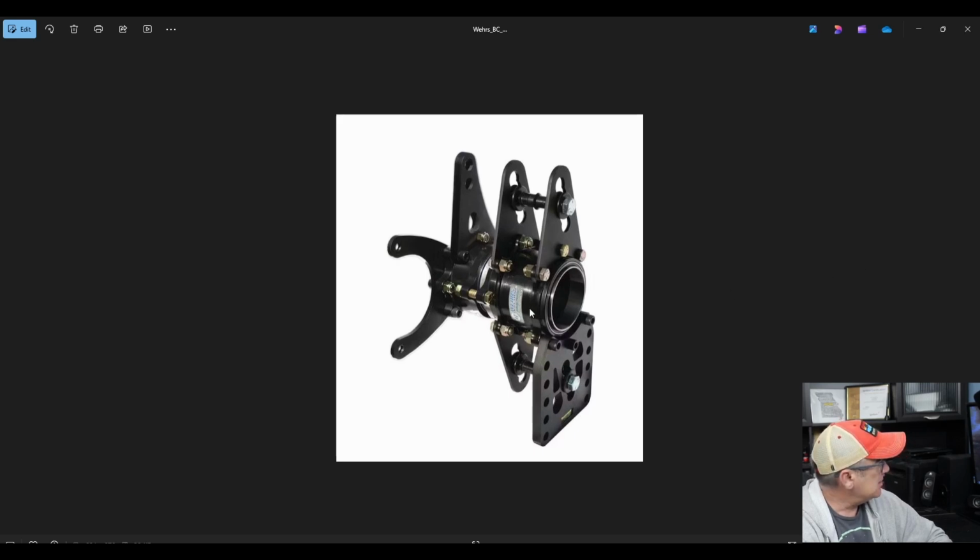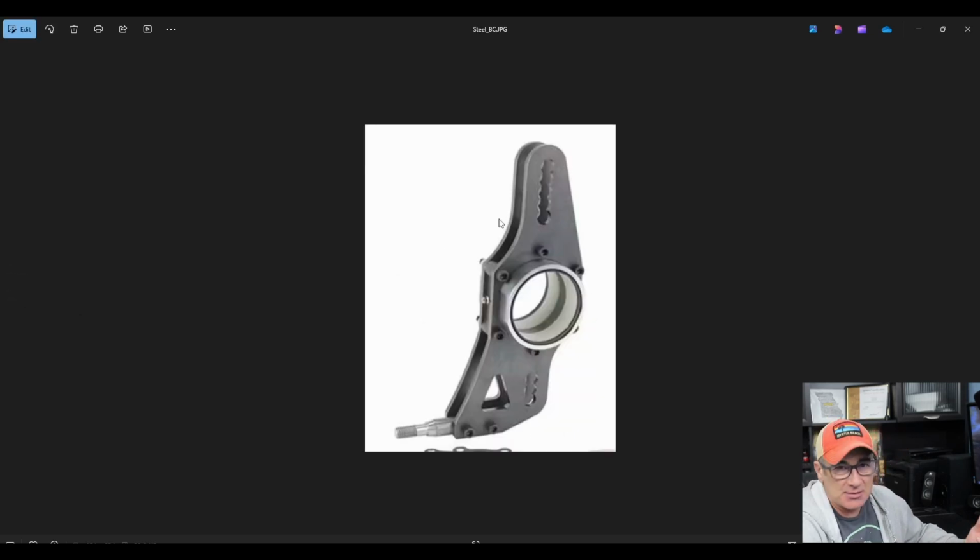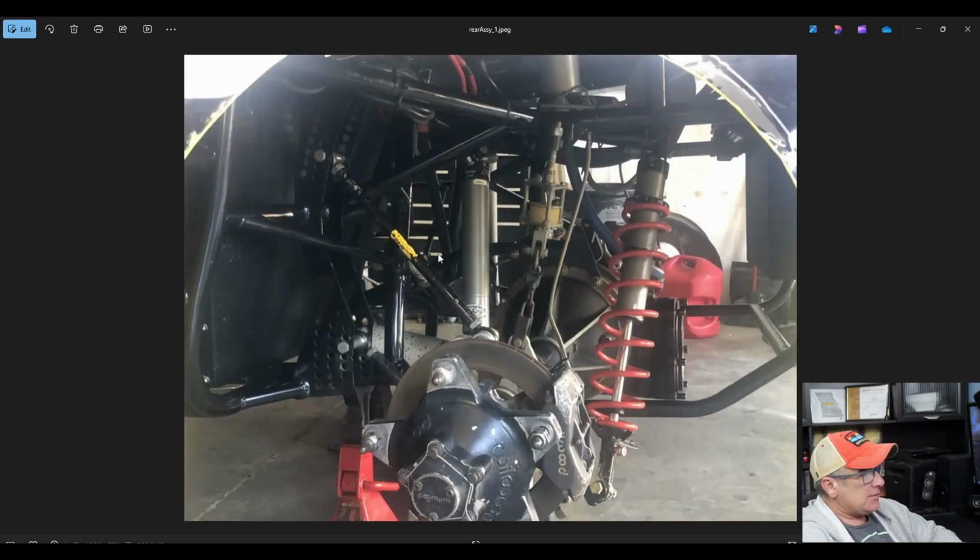But you can see that these can get a little more complicated. But the basic operation, though, is quite simple. It's just a couple of connection points for your 4-bar links, a connecting point for your spring, and a place for the axle tube, and something that allows that frame or that connection point, the birdcage, to rotate on the axle. And so that is a birdcage. Our 4-bar links, our birdcages, our axle assembly, our 5th arm.